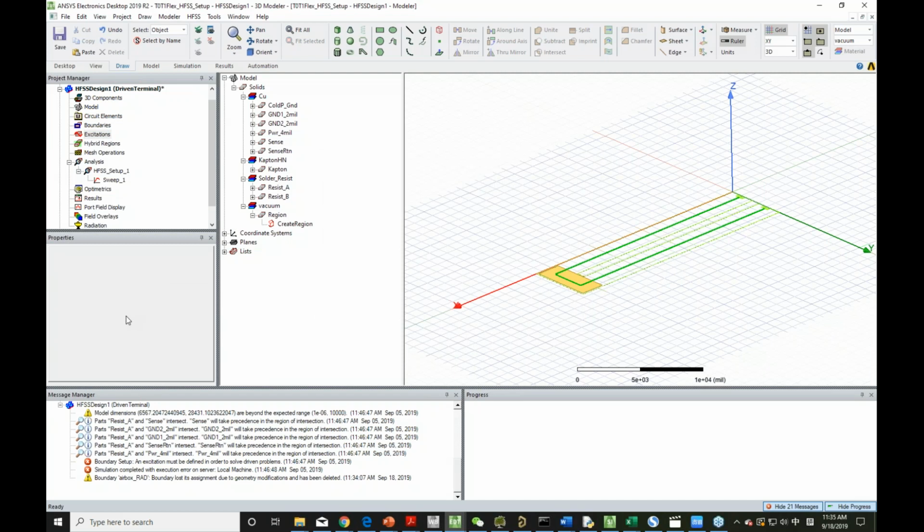I don't think the radiation box has anything to do with your optimal operating frequency. That's dependent on the excitations and your model design. If you like, you can send an email to support with your project, and we can take a look at it.